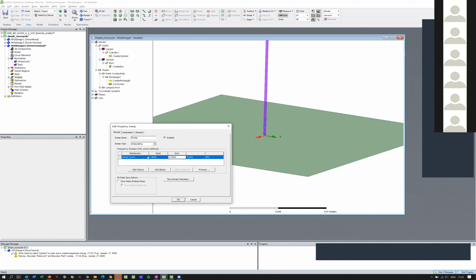So this is the range I'm sweeping my data points, and 401 is too much. I will limit it to 201. Basically, this is just giving us a kind of spectrum analyzer, sweeping a specific frequency band. This is doing the same, so this is equal to a spectrum analyzer frequency sweep.